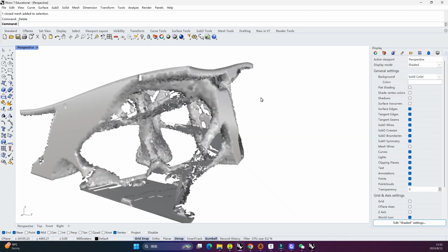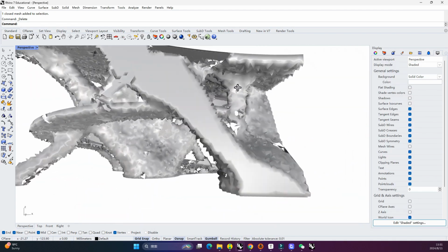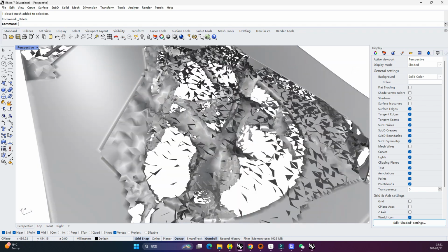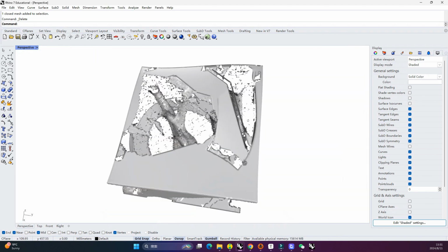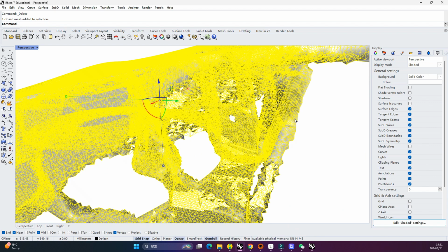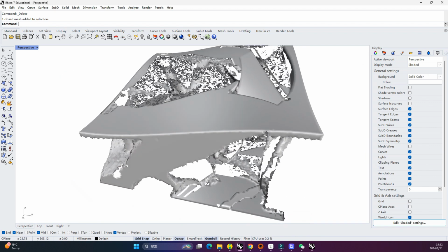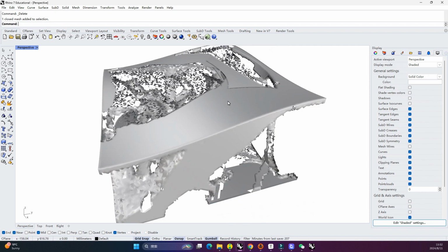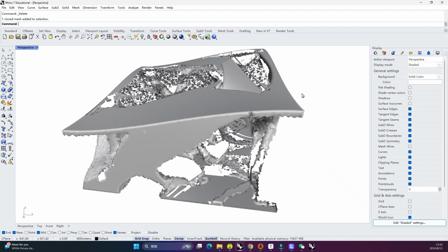And then, as you can see, the model has a lot of rendering errors. This is because of the non-manifold features, as we mentioned before. So, in this tutorial, we will use a very simple and commonly used method to fix this problem. In this case, we will use Rhino 8. Rhino 8 has a very powerful function called shrink wrap. So we can launch Rhino 8 first.